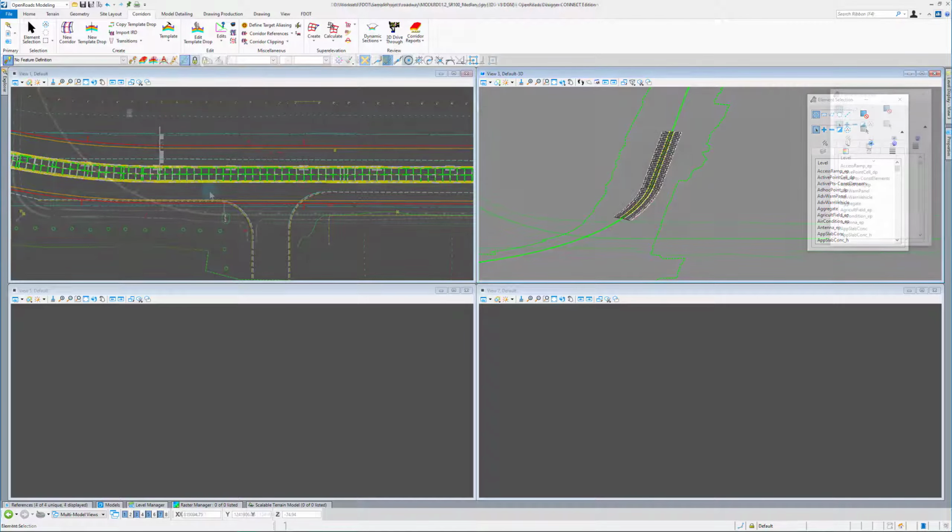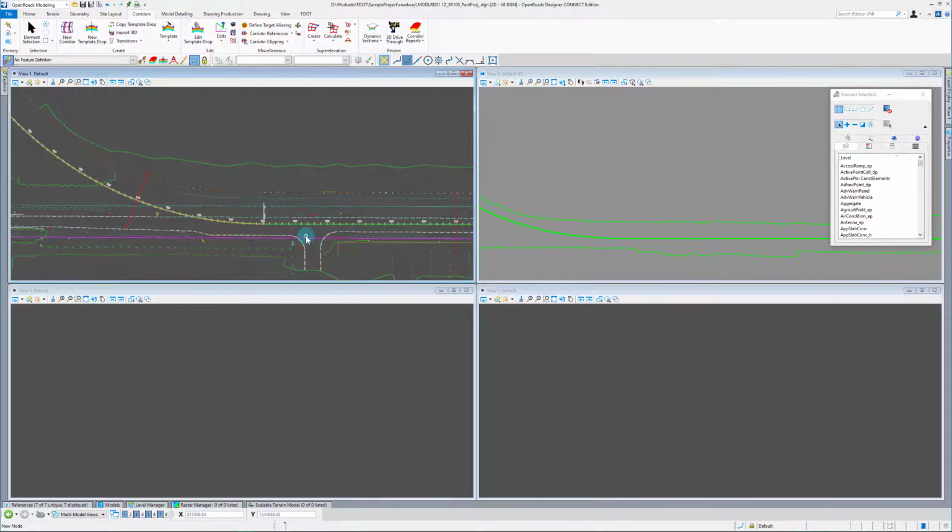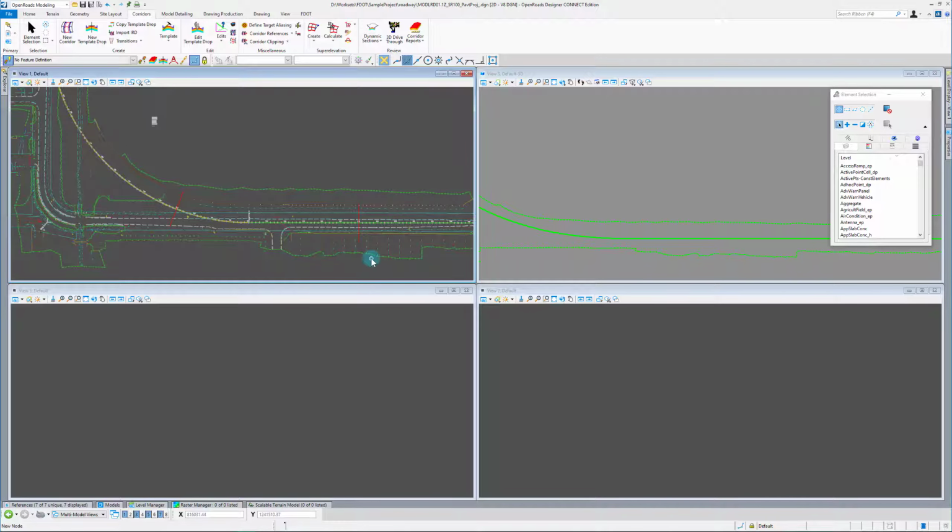Before we start working with some of our end conditions and side streets, I want to create a file that I found really useful. And this is a projected pavement file. So I'm basically going to create a dummy surface that projects my pavement out beyond the normal edge of pavement limits, as well as towards the median to give me a crown. And I found this really useful when I'm creating my side streets or when I'm trying to detail model a median. So I want to show you how to set that up.